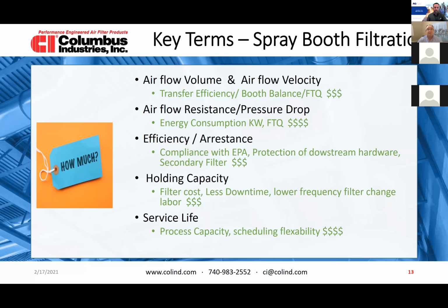If at one point you're doing your schedule and you need a little bit of an increment in your production, if you have a filter that can take a little bit more because of the higher capacity, then you're able to do that without having to stop and change your schedules and so on. So these are the factors by which these terms in spray booth filtration do affect the cost.